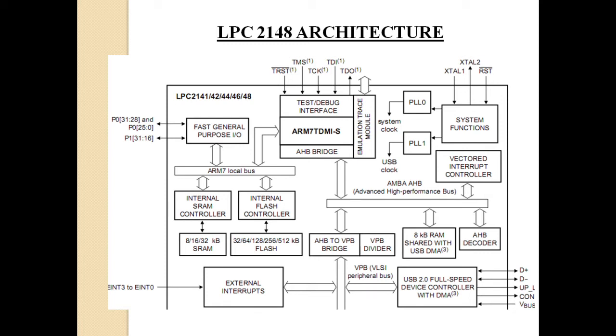right? But the problem with that is that you will not be able to produce an accurate clock. Say in the case of your laptop, you are telling that it is say 3.2 gigahertz. 3.2 gigahertz means always the processor should be getting 3.2. If there are some variations in the clock, the working will be affected. So the 555 astable multivibrator problem is that it is not accurate.